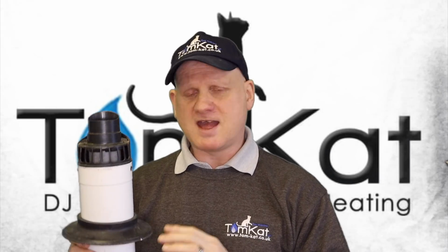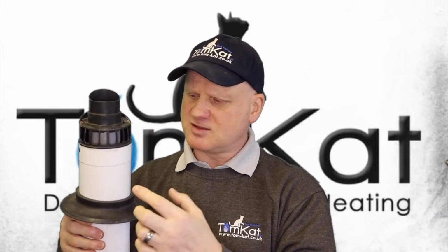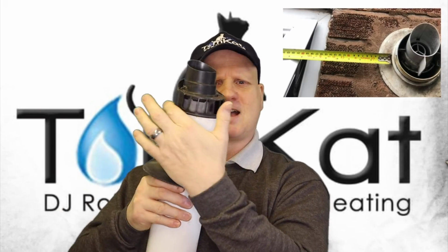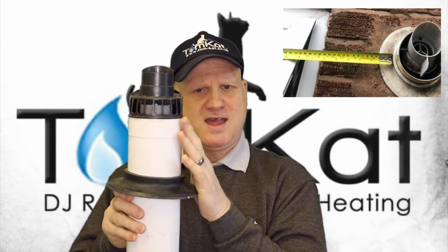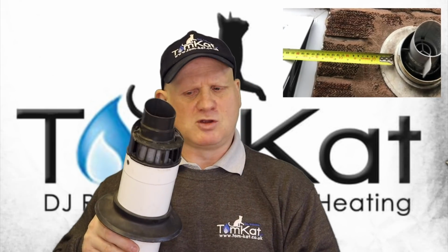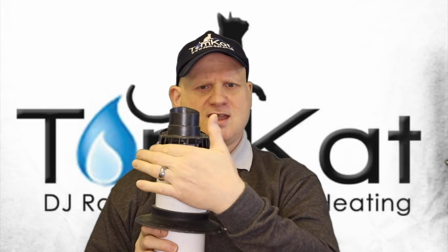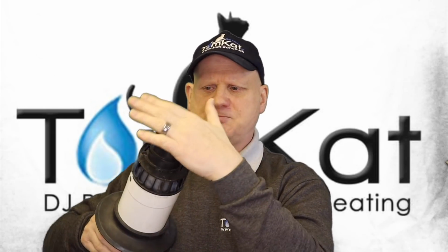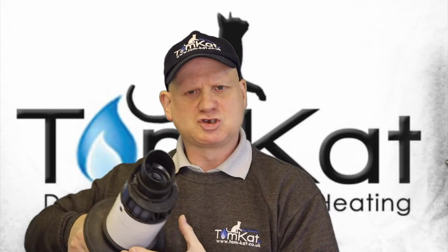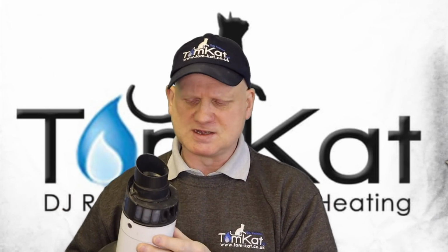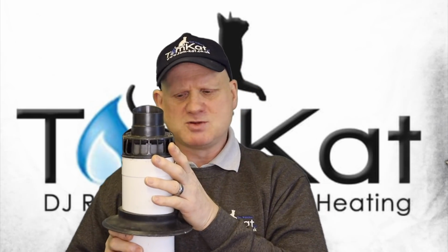Now, as I've just said, the measurements for the flue distances come from the bottom, the top, or the sides from here, not from the outlet side, but from actually where the inlet comes in. So this is the air inlet of this flue system, and this is the products of combustion out. They're not all exactly the same, but they're pretty much the same. So that's where the measurements come from.